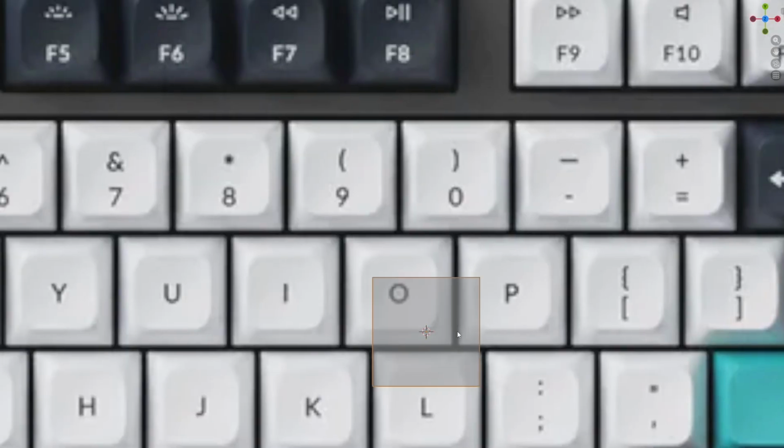In the top view, let's move the plane over one of the keys. Then inset the face by pressing I. Go back to the side view and move it up to match the reference. We'll start with this top row. Then select these 4 edges and press Ctrl B to bevel them, and we can scroll up on the mouse wheel until we have 4 segments.